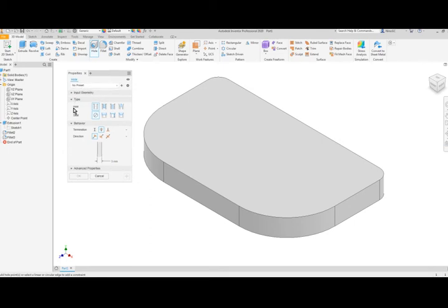We have the following. We have the types of holes, which consists of simple holes, we have clearance holes, we have tapped holes, and we have tapped tapers, which are NPT type holes. The seats themselves, we have simply no seats, which is basically a through hole. We have a counter bore, we have a spot face, and we also have a counter sink.